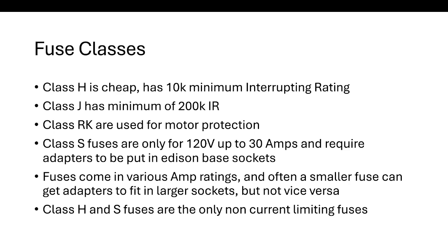Fuses come in various amp ratings, but often a smaller fuse can get adapters to fit in larger sockets, but not vice versa. That means that the fuse will trip before what the disconnect is actually rated for, but that may be useful in certain situations.